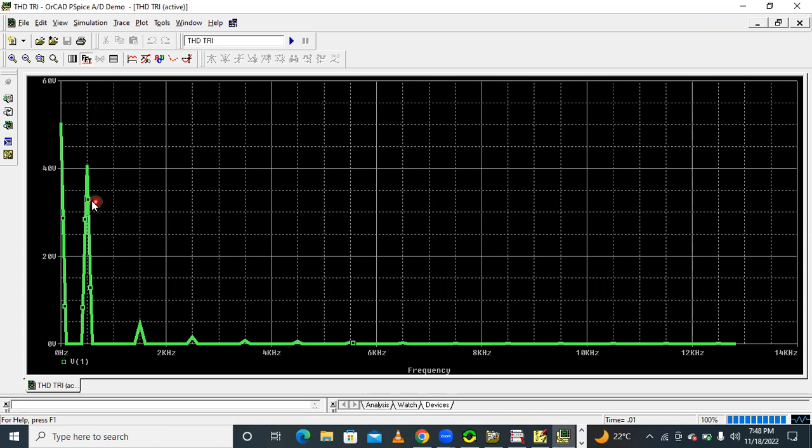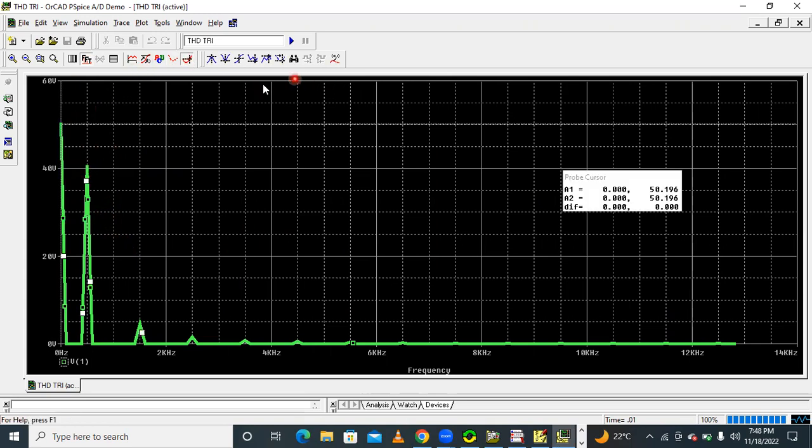Okay, in this harmonic spectrum, first this is called the fundamental. So enable toggle cursor and find the corresponding voltage. So here, approximately, place it like this, enable toggle cursor, and here mark label. So 497 means approximately 500 Hz, 500 Hz.